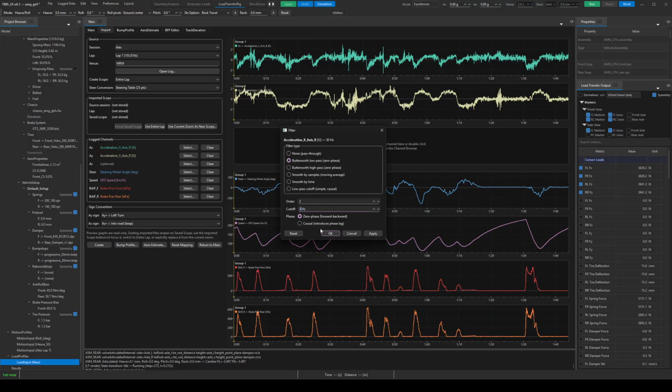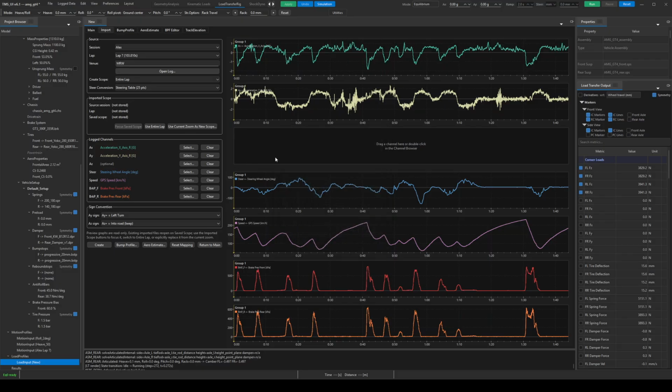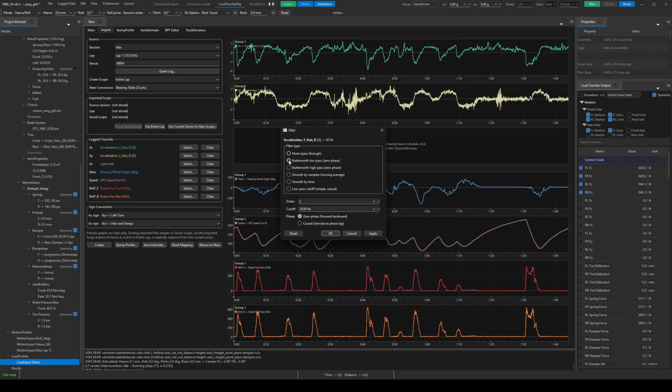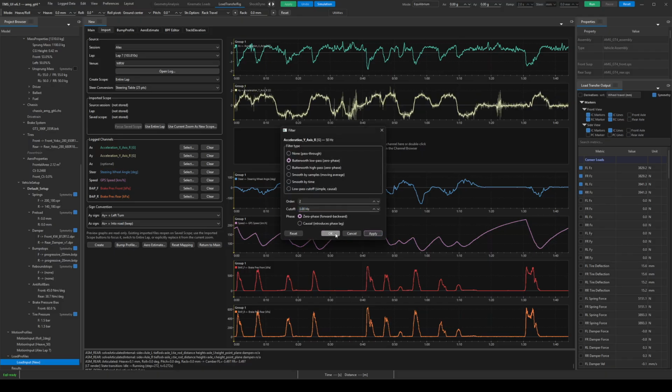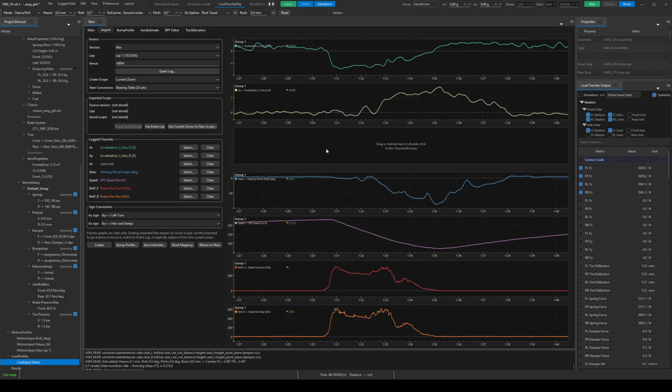At each time step, the rig calculates tire loads, spring and damper forces, anti-roll bar loads, and many other simulation channels. The engineer can then study what was happening in a specific braking zone, corner entry, apex, or any other part of the lap. More importantly, the user can change a setup parameter, rerun the same logged session, and compare the response directly. There is one important limitation.